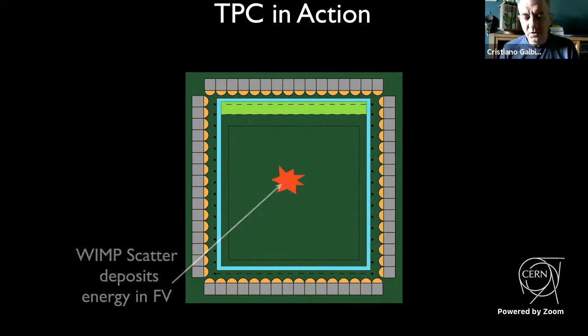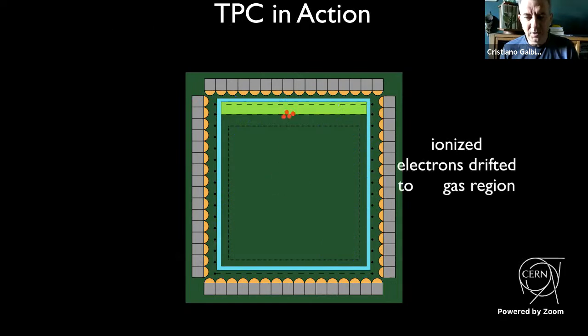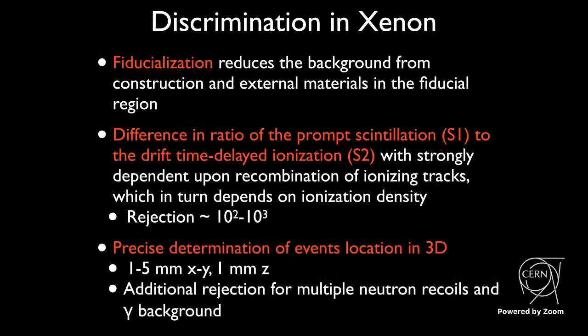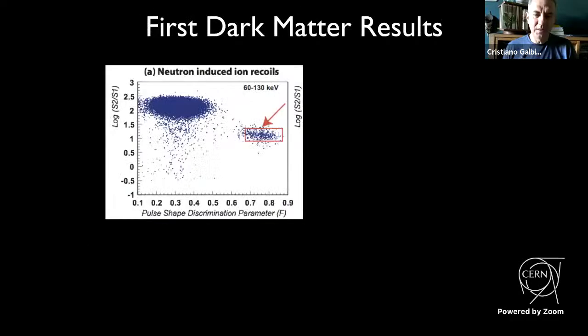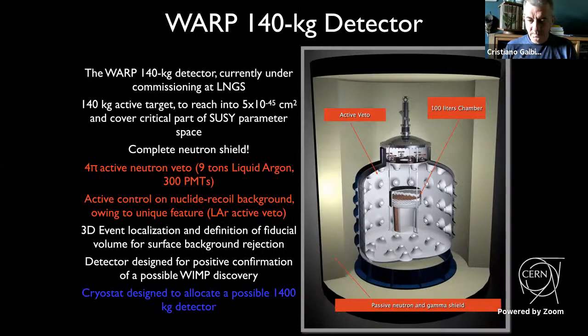So the silicon PMs, you're absolutely right. When we started the DarkSide developments, they were still being developed and they were not ready for use at the time. Now, the WARP detector was using just regular PMTs, regular for operation in liquid argon, and they were a nightmare. They were not extremely stable, subjected to discharges and so forth, because of this problem of the resistivity of the photocathode at liquid argon temperature.